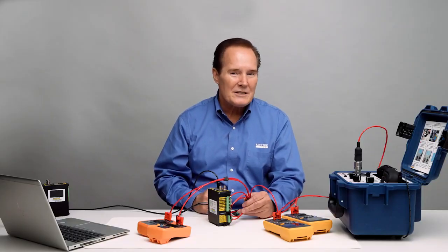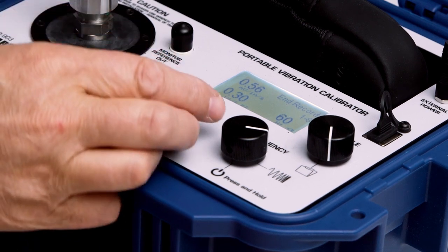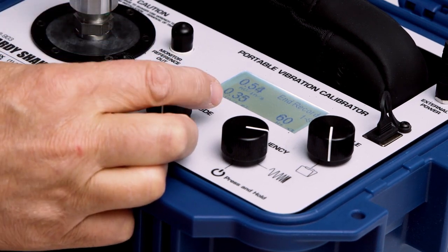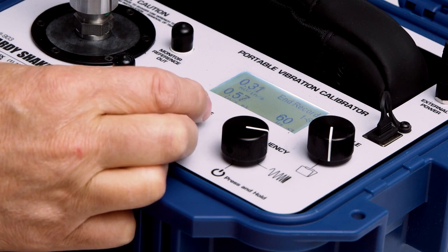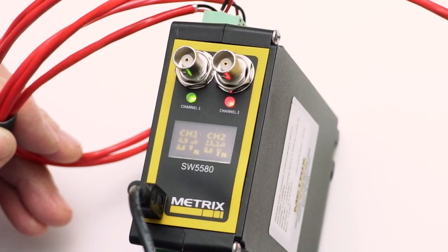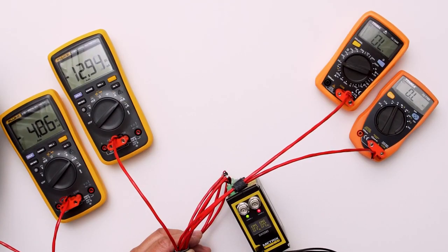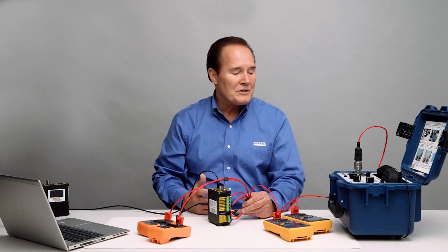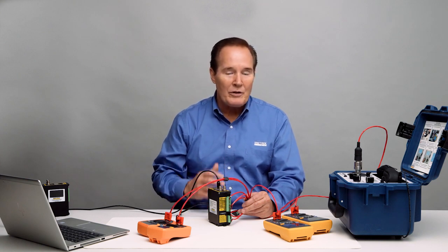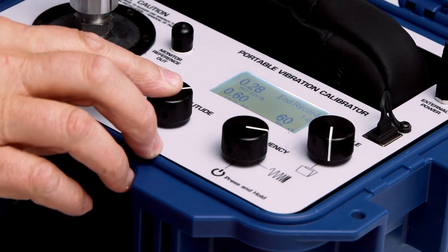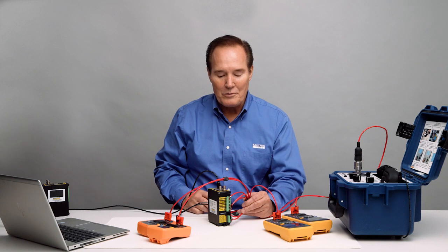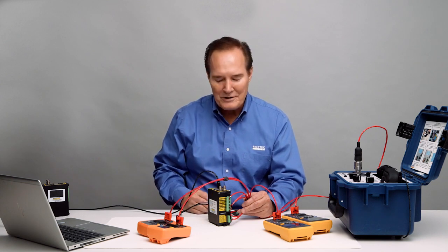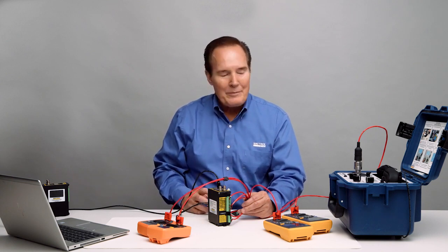Let's go to 0.6 inches per second. Okay, that's 0.6. Danger alarm comes in, flashing red. And that's what we expect from the system, so it's behaving exactly how we want. Now at 0.6, like I said before, we're only about 0.5 Gs, and we'll see that if we switch to Gs on the shaker. We're at 0.6 Gs, almost the same. I guess at 60 hertz it's very close. So that makes sense, so that's good.